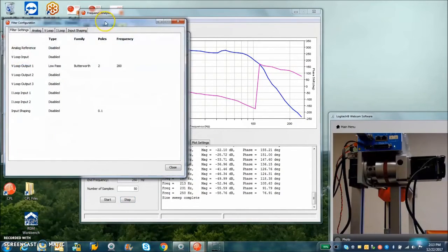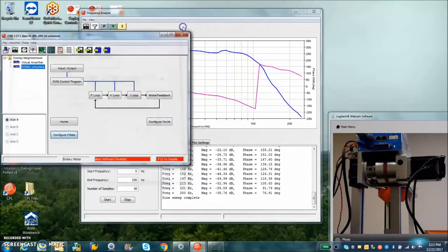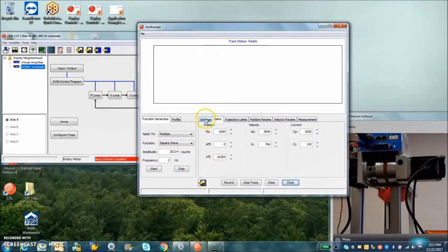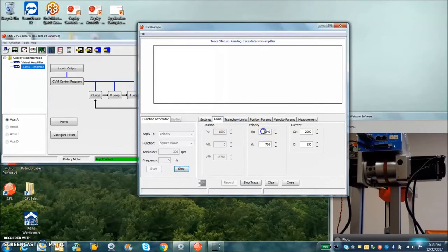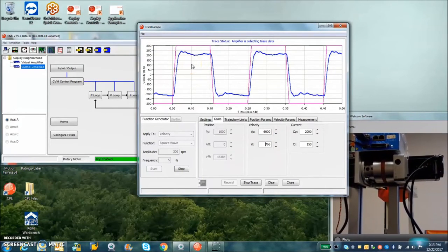This is explained by the pole at the output of the velocity loop. It's a 2-pole. We can switch it to a single pole, and that'll move out. So we're going to take a look at the tuning of the velocity loop in the normal way now, and we'll see what we can get out of this tuning here. So again, if my gains are too high for my BP, I'll start seeing ringing.